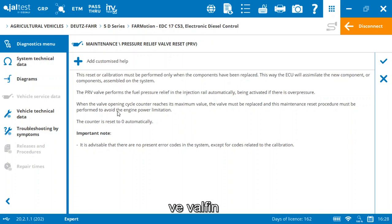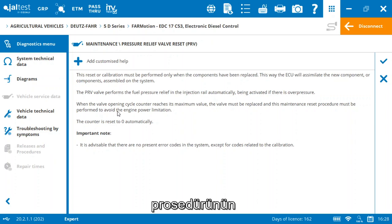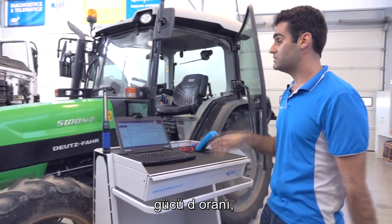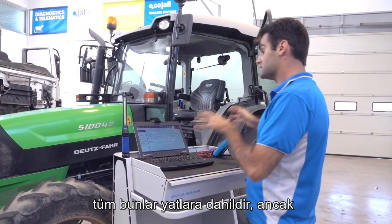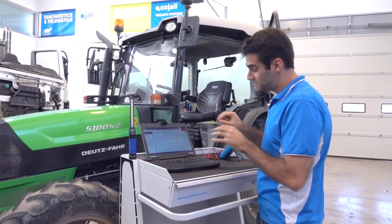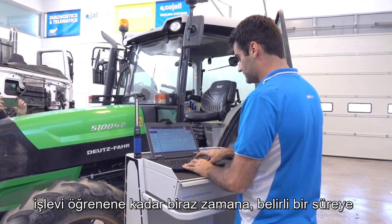Keep in mind that the valve must be replaced and this maintenance reset procedure must be performed to avoid the engine power limitation, the engine power derate. All of this is included in Jaltest, but we need a certain amount of time, a bit of patience until we get into the correct function.